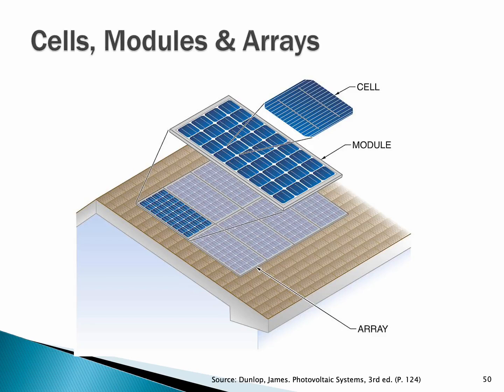some more review. We have a cell, and a group of cells make up a module. The correct term for this, the code term for this, is module. Even though in solar literature and when we talk, we call this sometimes a panel. It's not a panel. A collection of modules that are physically connected together is called a panel, and a collection of panels makes an array. So we could have a panel that is also an array, one panel making one array, or we could have multiple panels making an array too.